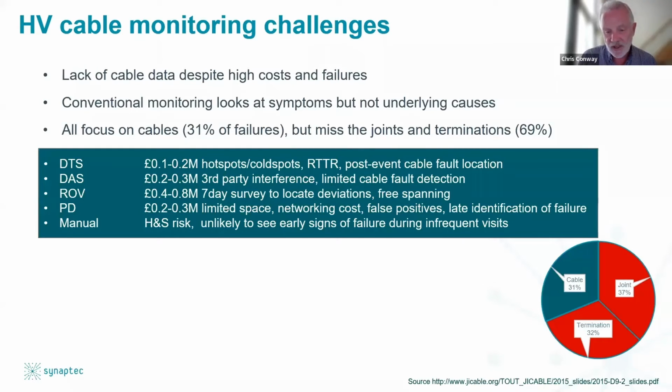DTS is effectively a fiber inside a power cable used as a distributed temperature sensor, measuring temperature profiles along the cable. So it's very useful for looking for hot spots and cold spots that might be a symptom of cable deburial, and also for use with real-time thermal rating.